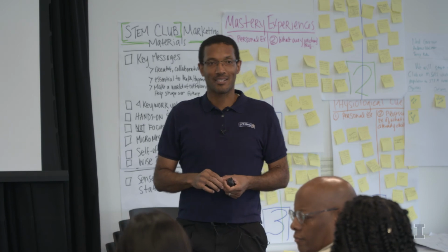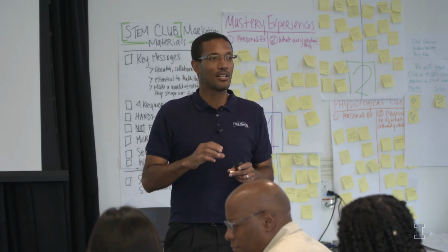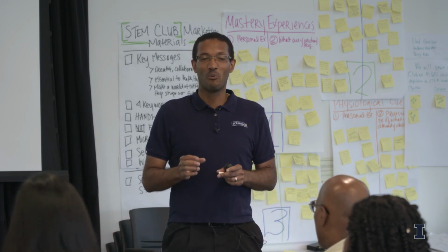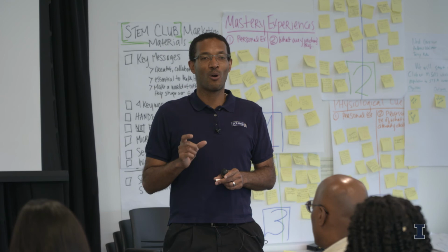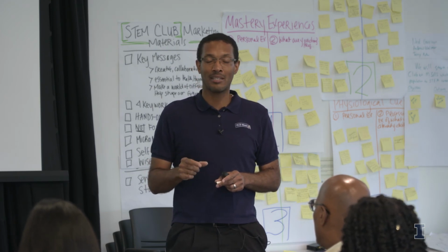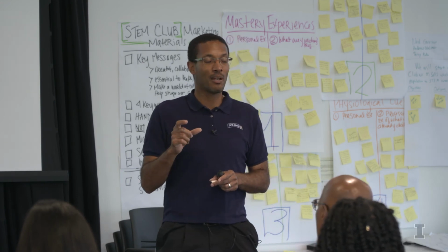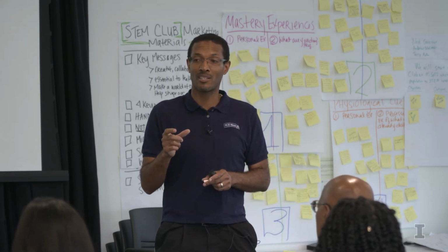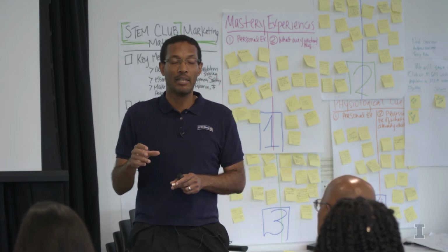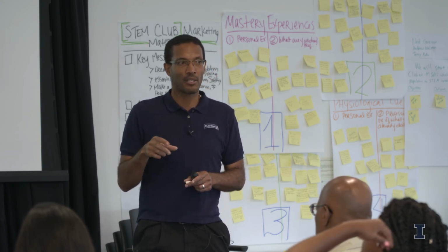Now, in practice, and this is an important point, this activity is to teach design of experiment. It doesn't teach good circuit practices. When you work with LEDs, you want to always have a resistor in series with the LED. The reason is the LED is a current-controlled device, meaning that if I apply 5 volts across an LED, I'm going to burn it out because the current that flows to the LED will be really high. I need a resistor to limit the amount of current that goes through it.